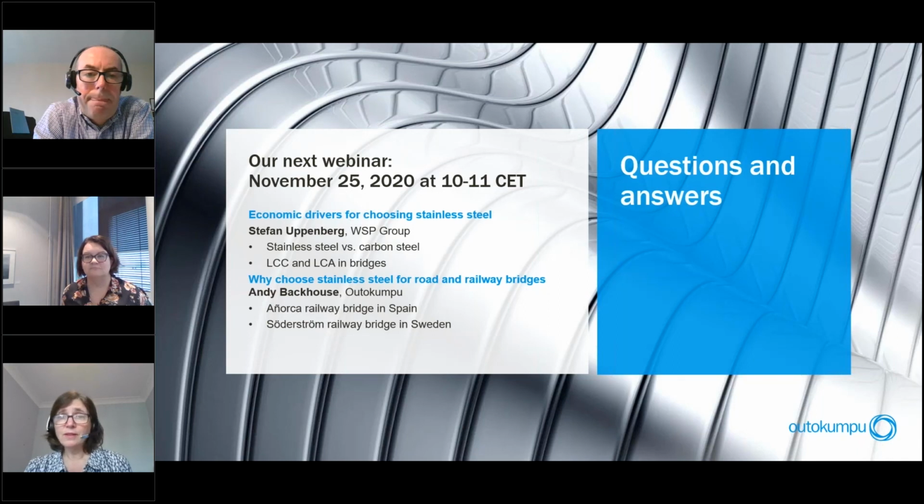For welding duplex, you need tighter controls when it comes to heat input, and I recommend a particularly good technical brochure on fabrication of duplex stainless steels produced by the International Molybdenum Association, which goes through all the issues in great detail.